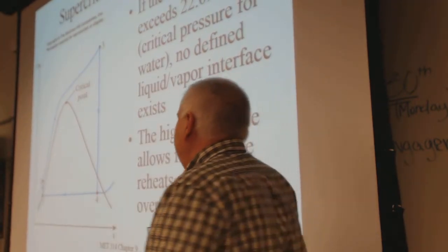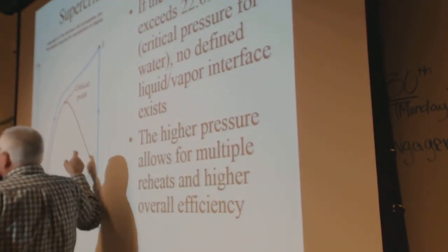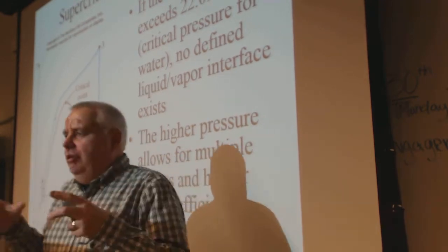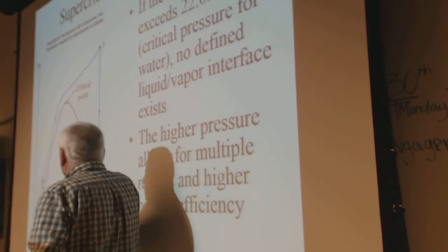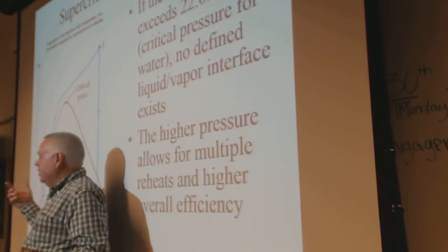It gets more complicated, and then they also have things where they'll take some of the steam that's leaking, because they'll also have the seals leak. And they'll capture that steam and channel it into feed water, sort of like the regeneration on the Brayton cycles.